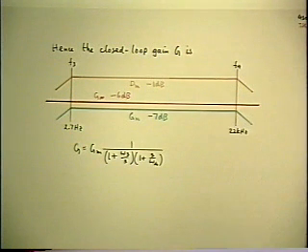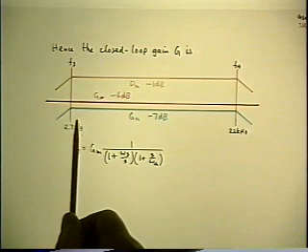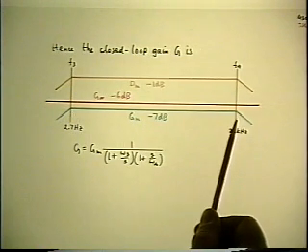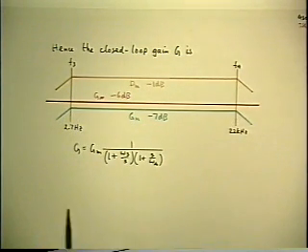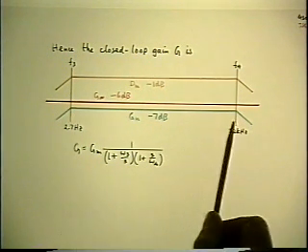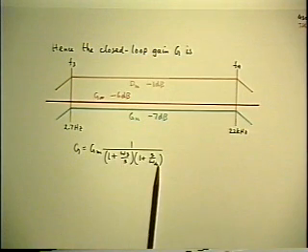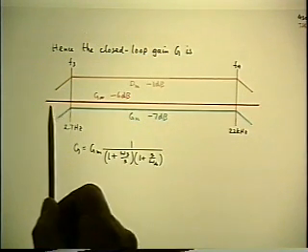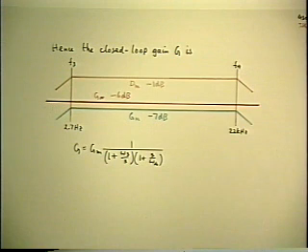This is where the benefit of the design-oriented analysis comes in, because in order to get required values of those two corners, you're going to have to work back to what corners are required in the original circuit. Well, what are these corners? They're the omega 3 and the omega 4, which are the zeros of f, which are the roots of that quadratic equation.